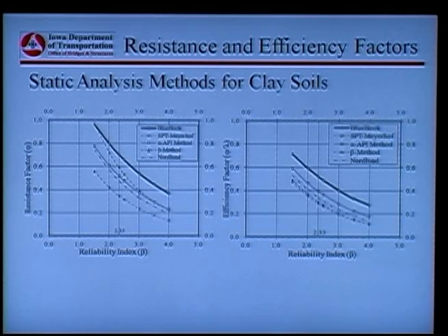Right? And for each of the methods, we use the Blue Book, we use other statistical methods, but we want to know which method gives you the best efficiency in terms of estimating the pile capacity. So if you look at the solid black line, that is based on the Iowa Blue Book. As compared with the other methods, we found that the Blue Book, among the others, gives you the best estimation of the pile capacity.